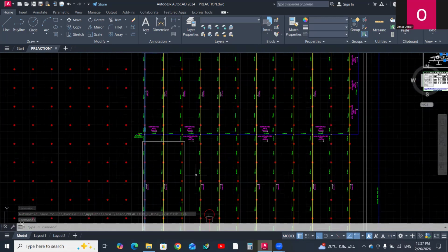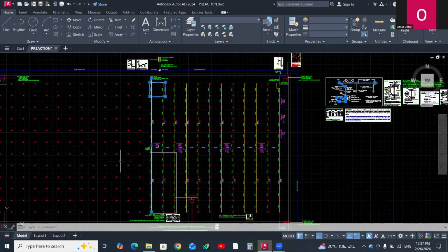Also, you have to note to facilitate the drainage and flushing of the network after testing or after a fire condition. If the warehouse freezing system activates, the residual water inside the pipes will also freeze inside the pipes. So you have to ensure all water has been drained from the system.